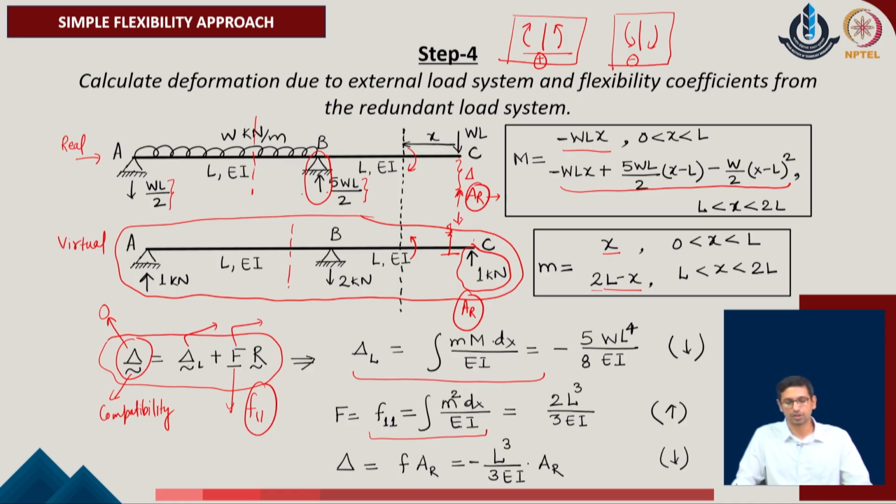To consider this part, we include here the amount of deformation due to the spring component, and that is included as the flexibility of the spring times A_r, which is the force in the spring component. We must repeat that as we are considering the spring to be over here, the force which we consider as the redundant, the same equal and opposite value will be translated to the spring component, and that is why the force A_r is considered to be active in this spring.